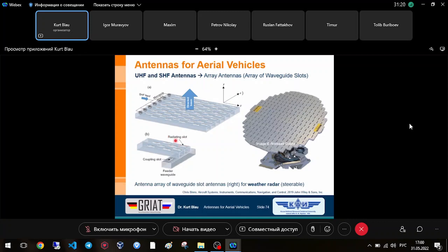It consists of radiating slots. You see here in one waveguide, we have slots left, right, after a certain mathematically based arrangement. The distance to the edges and the distance of the slots to each other, and the distance between the slots in this direction, must be calculated, and it's not possible to make the slots after your mood.